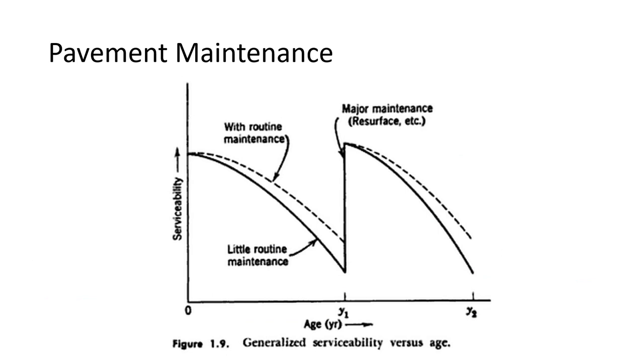And you might remember this curve from before. This is how pavement deteriorates. You've got a serviceability index over here, and this is the age of the pavement. You start out, everything's great. We usually say this is like a 5 or a 4.5 here, and then it drops. And it doesn't drop linearly. The speed that the pavement starts falling apart picks up as time goes on. So keep that in mind. It's not a linear thing.